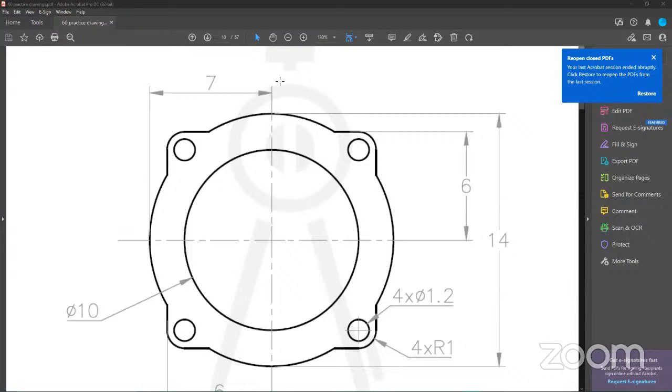With this, you have to use the line command, you use the circle tool, you use arrays if you want to, or you can decide to mirror and create one and mirror them. And then what else? Some people will use a rectangle first, and then they trim off some unnecessary parts and leave the rest.